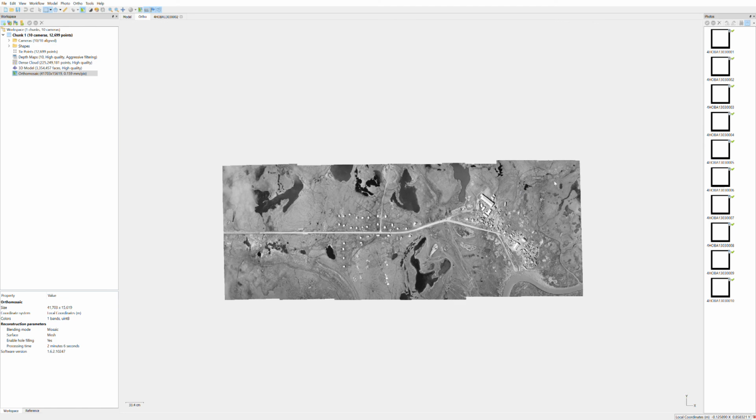And then once it's georeferenced, you can use the tool Define Projection, and what that'll do is you can tell the program what projection this image is in, and then it won't move around. It'll be all happy. You'll have a perfect ortho from 1975. Alright, thanks, and I hope that works out for you and you don't run into any issues like I did. Wonderful.